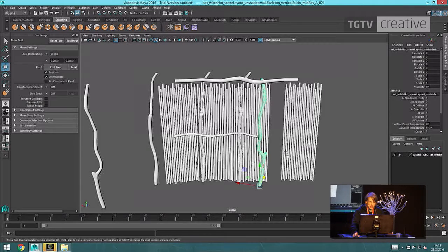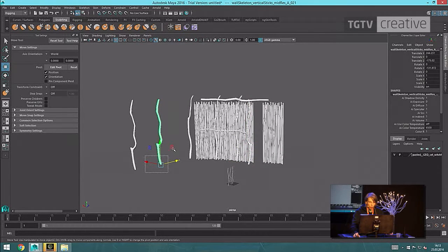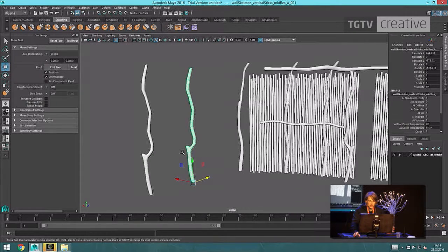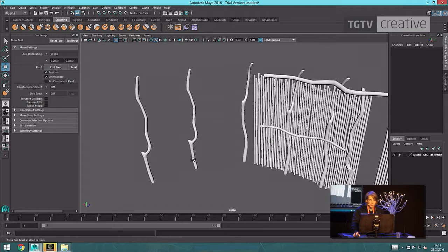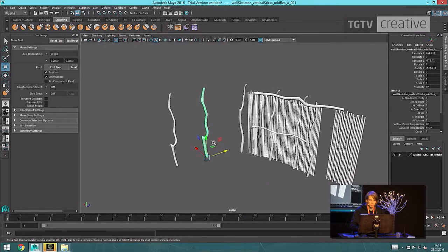So the good thing about this is that if you make a kit that has only the essentials, like 5 branches, 5 bamboo sticks, and then 5 smaller branches that you can construct the whole hut with, you can have them all share the same UV tile, so you only need one texture map to make the textures for the whole hut. And so it's really easy to make changes to the textures and work iteratively when you know they're made from the same base components. It's pretty much like making your own advanced Lego bricks and then constructing the scene with them.